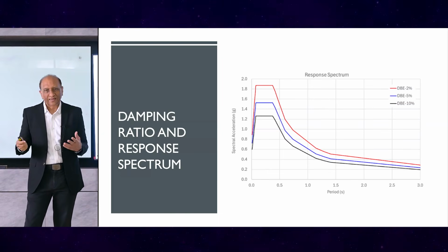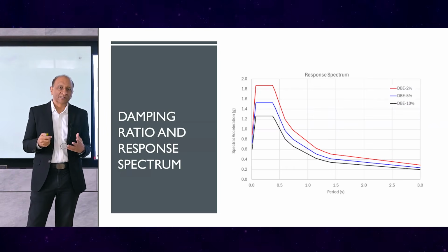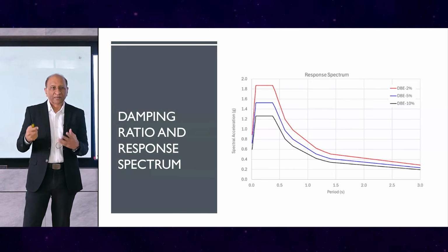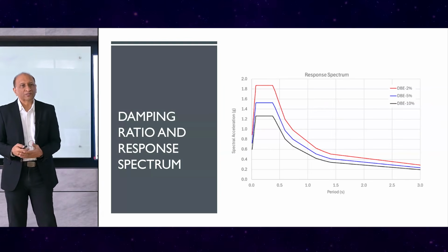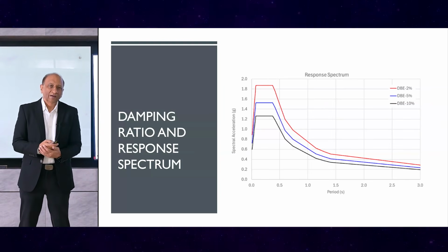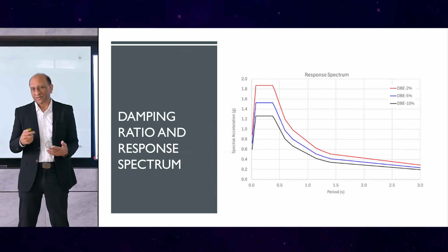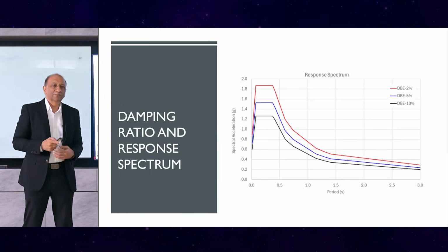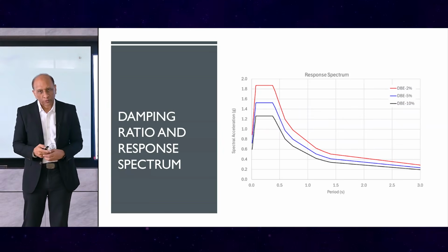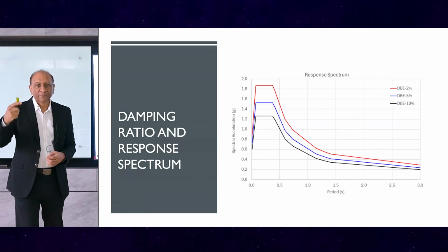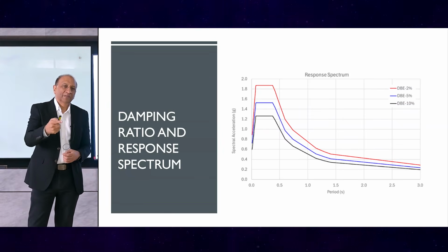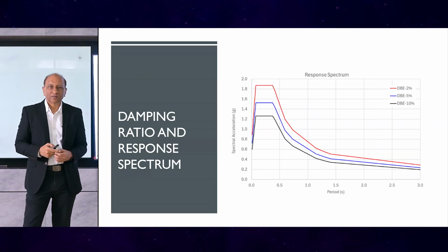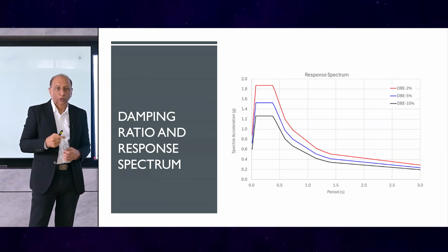In fact, a lot of researchers are saying that this 5% damping that we assume is too high. Real structures, especially the new ones, have much less damping, maybe 2%, maybe 2.5, maybe 1%. So if that is the case, then the response spectrum that we use to compute the forces will be far less than the actual response of the structure for a low damping.